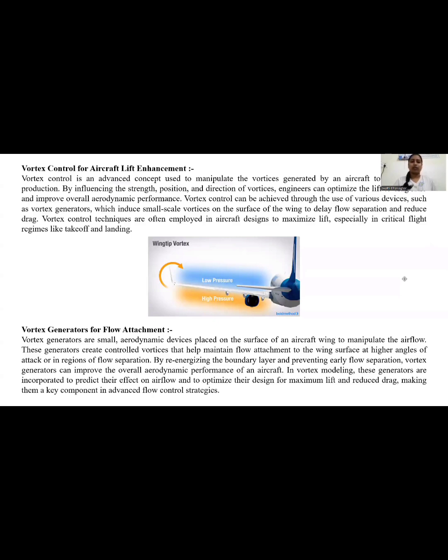Vortex control can be achieved through the use of various devices such as vortex generators, which induce small-scale vortices on the surface of the wing to delay flow separation and reduce drag. Vortex control techniques are often employed in aircraft designs to enhance lift, especially in critical flight regimes like takeoff and landing.